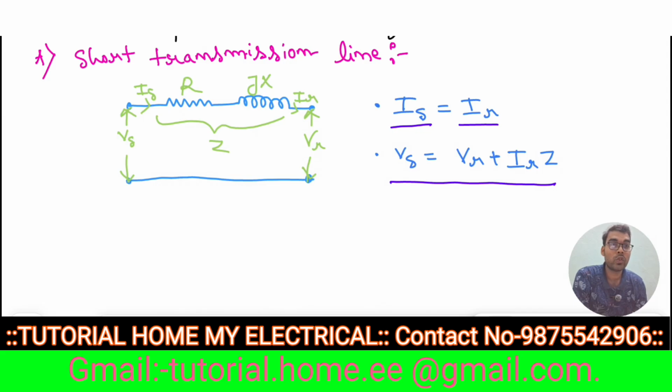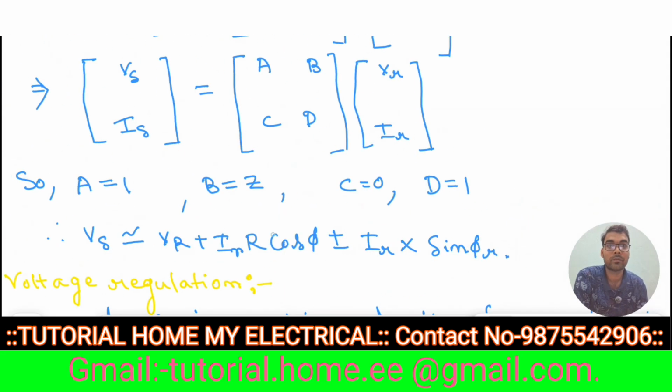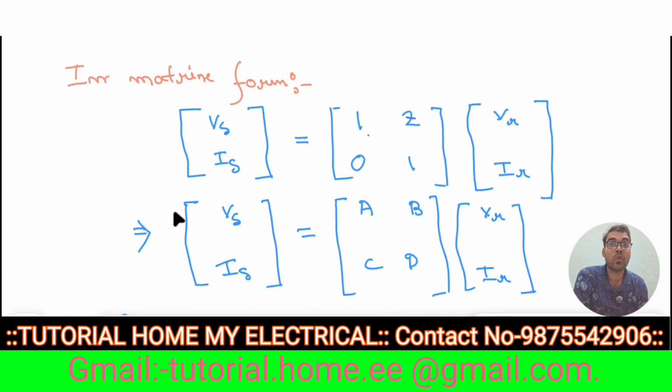Now we have to calculate the ABCD parameters. If we write the matrix of the short transmission line, then [Vs Is] is equal to [1 Z; 0 1] times [Vr Ir].